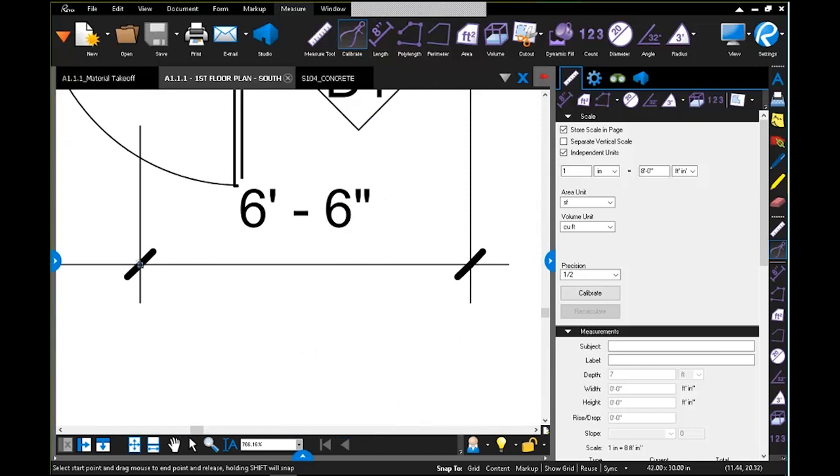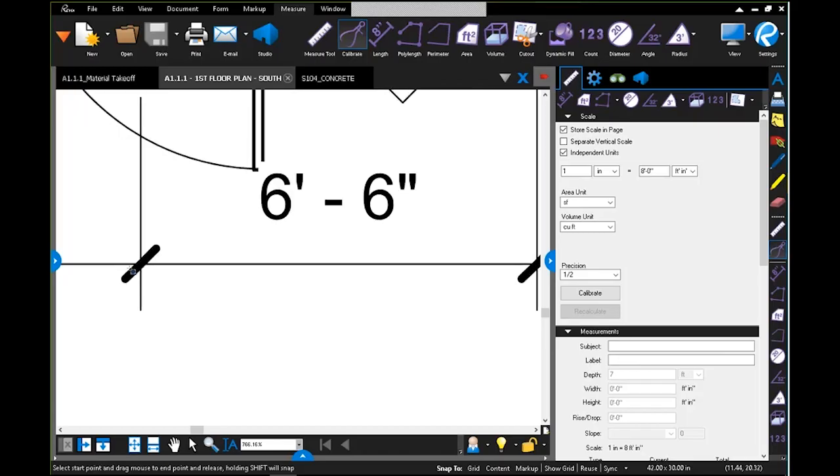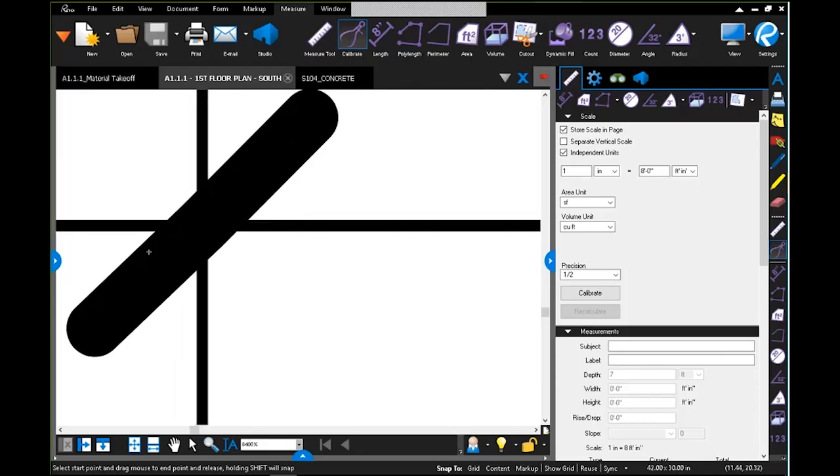Now, a vector PDF tends to be a document that comes native out of its original application. A scanned document, like I said, is a scanned document that you convert into PDF. You'll notice that when working with a vector PDF, you're able to snap into those endpoints fairly easily, as well as being able to zoom in without losing the image quality.